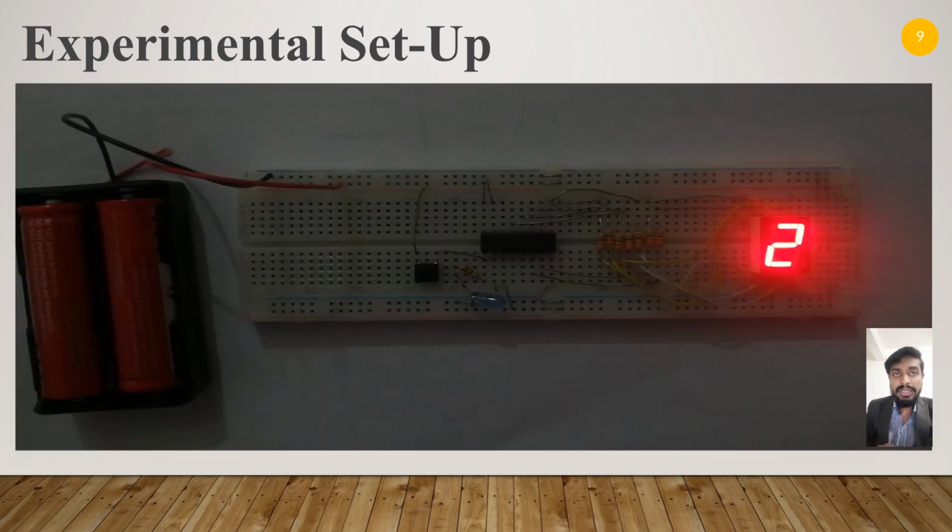In this circuit, we use a 1 kilo-ohm resistor, also known as a pull-down resistor, to keep the logic states of pin 1 and pin 15 low. Without this resistor, the electrical state of the pins would remain floating, making the circuit unstable.